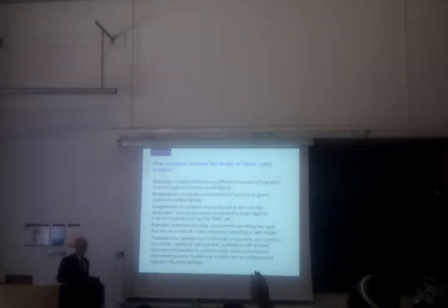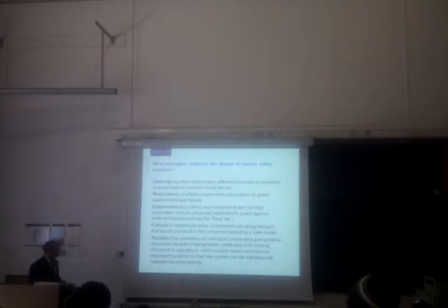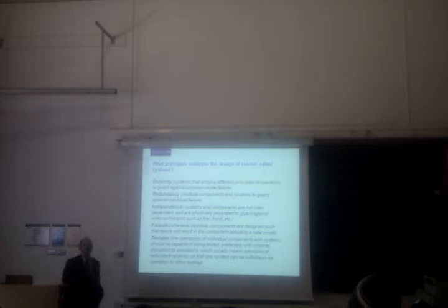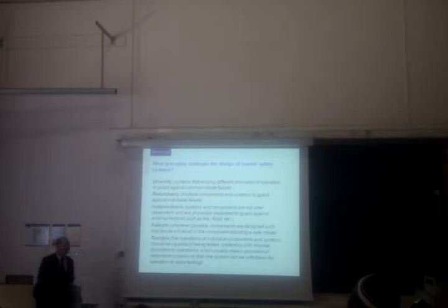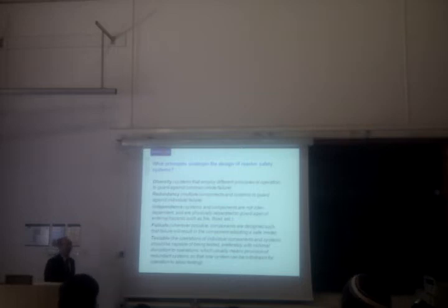Boron dust. Boron dust in the Magnox stations, yes. The secondary shutdown system in many Magnox stations was boron dust. It probably would have operated very well, but we don't know because we were never able to test it, not fully anyway, in a full operating station, because we would not have been able to recover the dust. So if you can remember that: diverse, redundant, independent, fail-safe and testable, easy box.